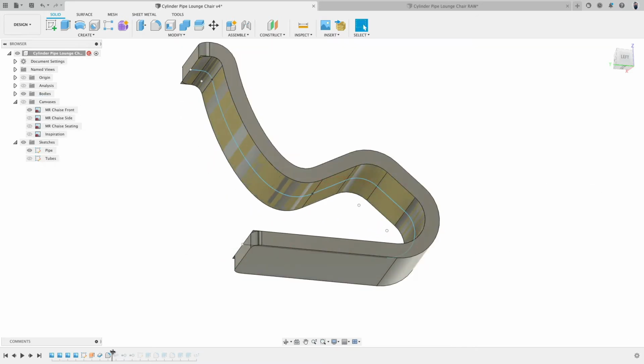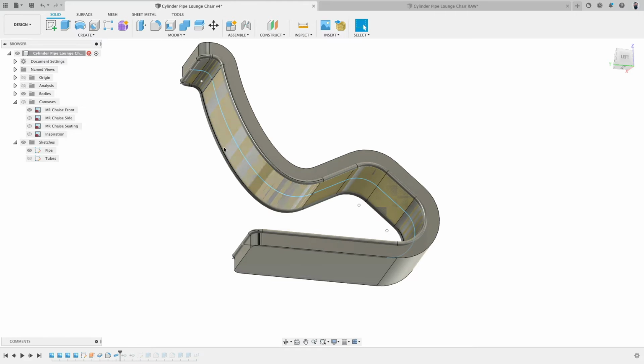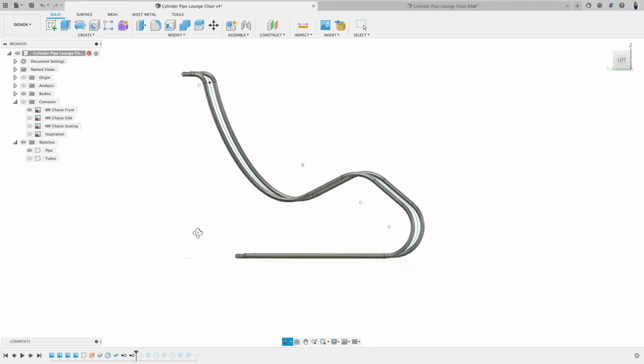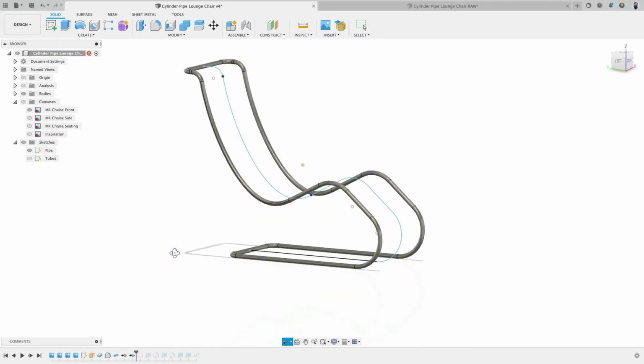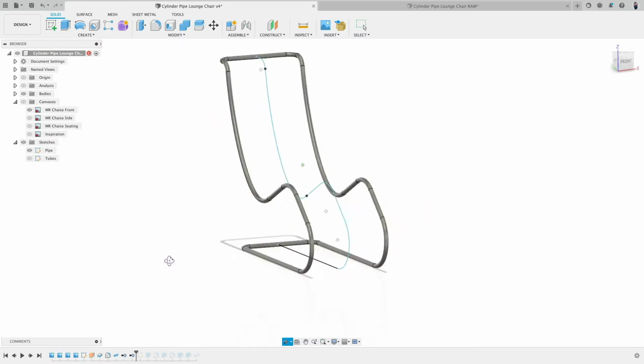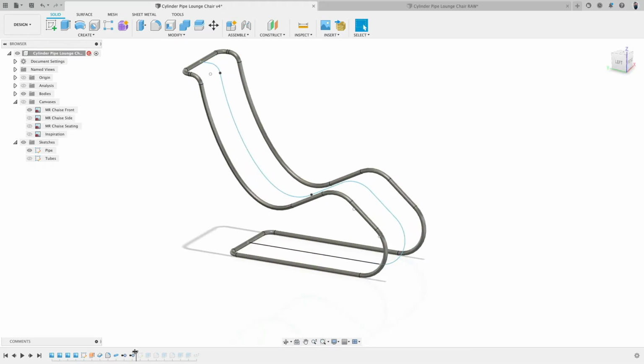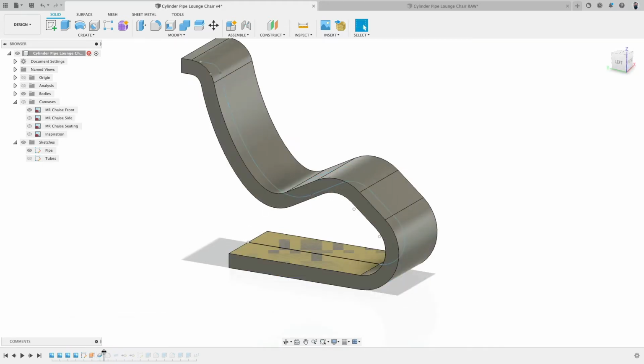Okay. So there's now the pipe and the inside. That's the reason why I extrude it to the outside for the thickness. I can remove this. Yeah, and there we are. There's the pipe. Super easy to create this kind of complex bend by simply making a flat surface, thickening, rounding edges, and piping it.